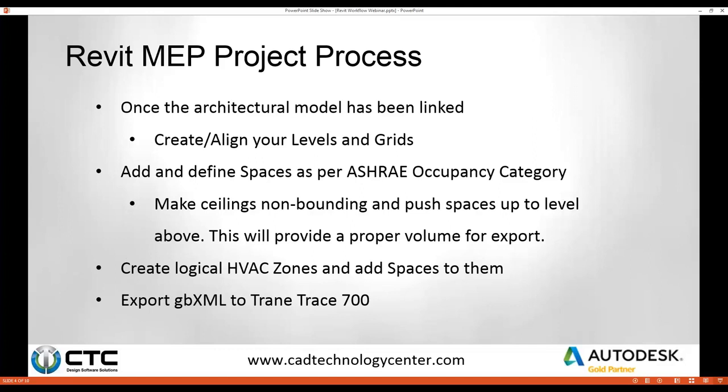Rather than going in and adding a plenum space, we can have the full volume of that space, and then once it gets into Trace, they don't have to go and delete all the plenum spaces, push the volumes all the way up to the roof or the next level, and then provide a plenum offset. They can just go right in and get the correct volumes and run the calculations.